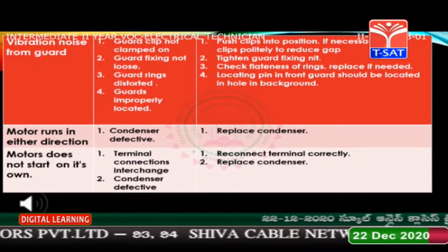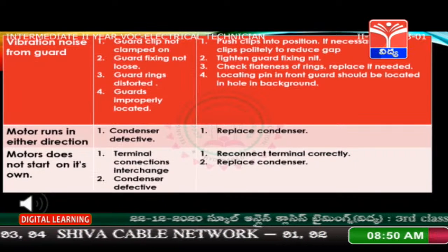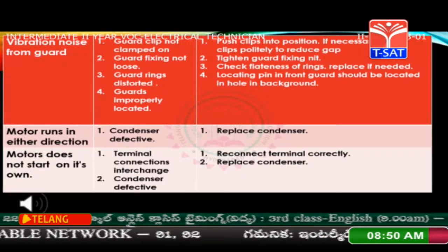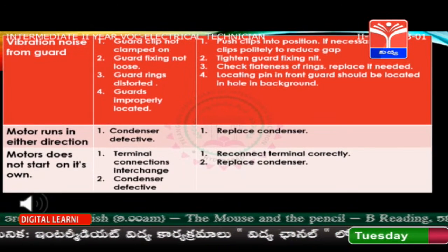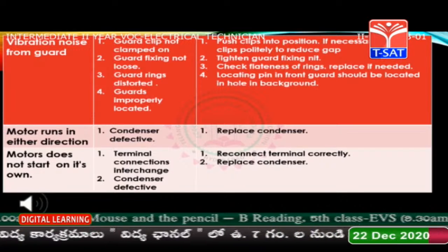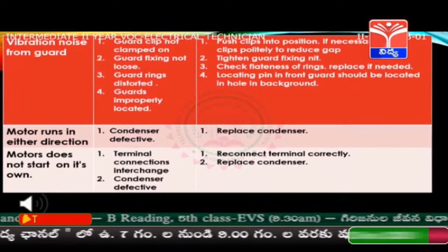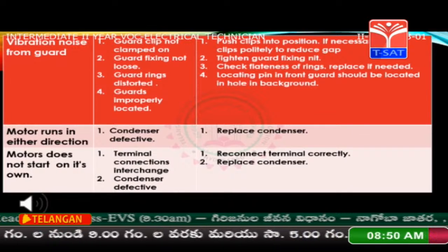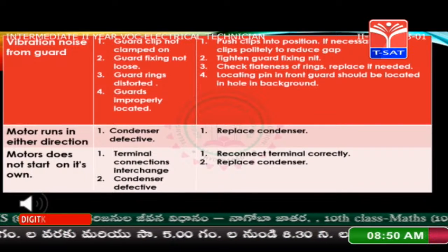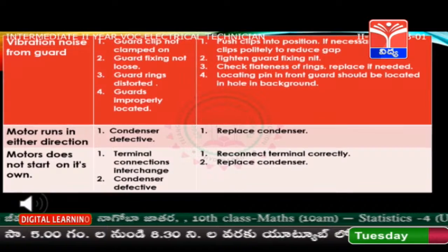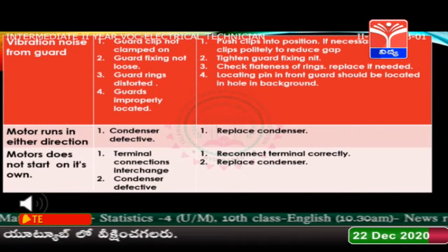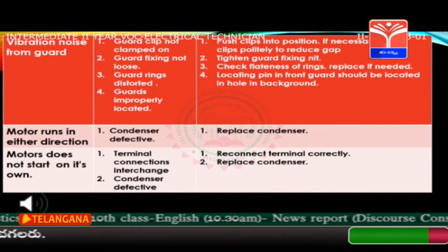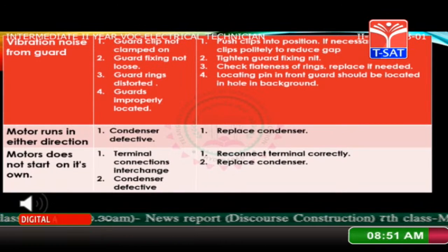Check flatness of rings. Reason: guard rings distorted. Remedy: replace guard set if not possible to correct the flatness. Reason: guards improperly located. Remedy: the locating pin in front guard should be located in hole in back guard.